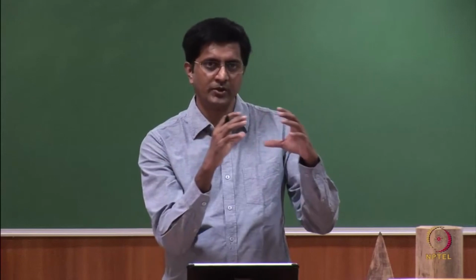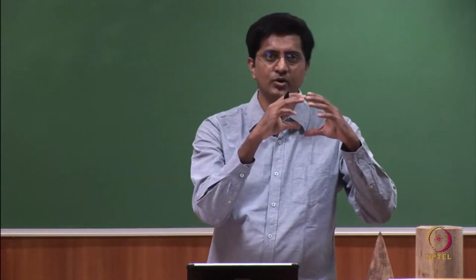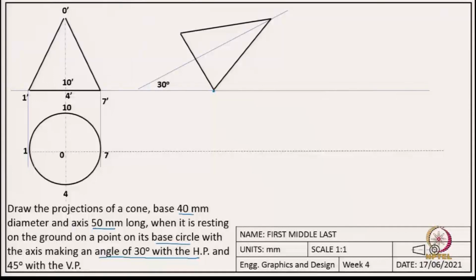We first, in the previous view where we had a circle, divided it into 12 equal parts. So, we had these points 1, of course 2, 3, 4, 7, 10 and 11 and 12. Okay. Similarly, you project these points onto the triangle, so that you identify these points. Now, by using these projection lines, both from the front view as well as the top view of the previous step, we identify the intersection of those points.